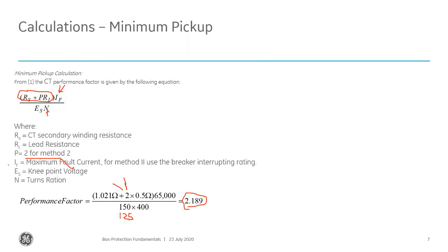Terry, is there any kind of guideline on if I've got a bunch of CTs, when I just keep paralleling them to the next one and the next one, and when I need to bring them all back in parallel? So one of the things that you should try to do is keep... What I often see, like in a switch yard, is there is a paralleling cabinet.